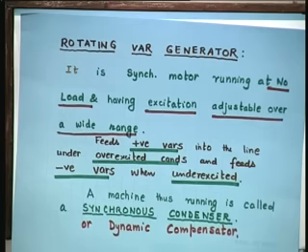A machine thus running is called synchronous condenser, synchronous compensator, dynamic compensator. There are several names given in the literature. That Miller's book I was referring to last time, please do read it, in 82, that is John Wiley, reactive power control and management.